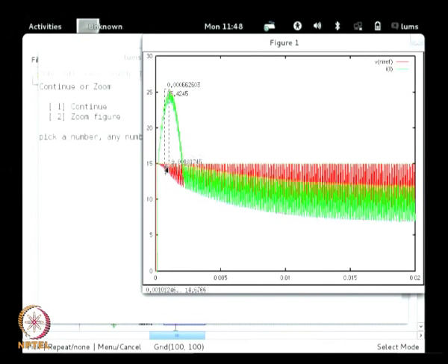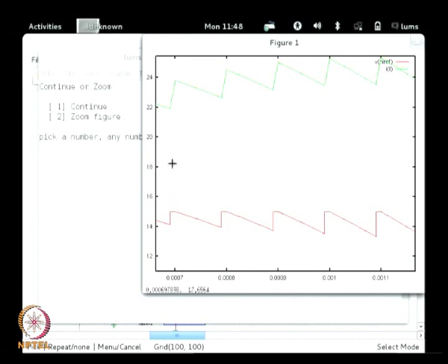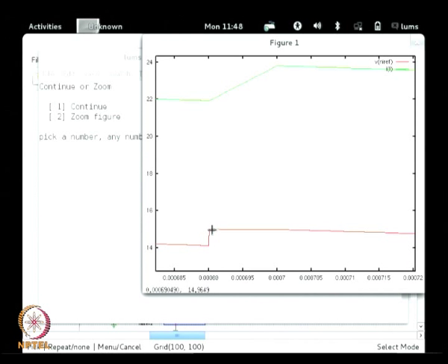So, you can see that in this portion, the inductor current rises only during the portion when the clock is in existence, and then after the clock goes off, because the current is higher than the reference current, it will start decaying immediately.